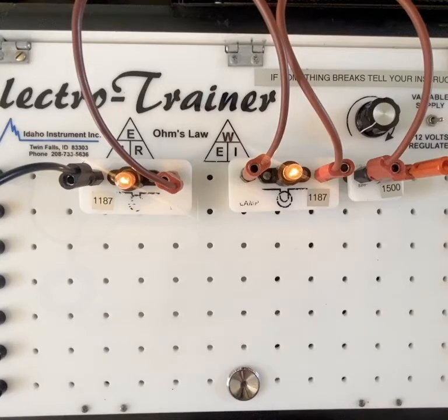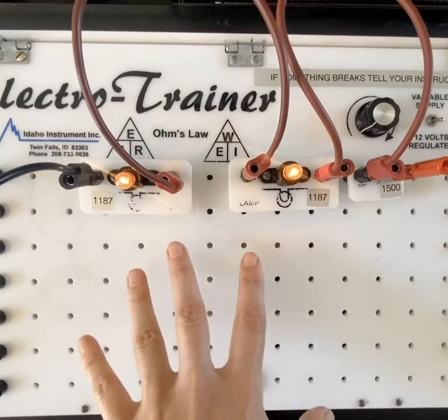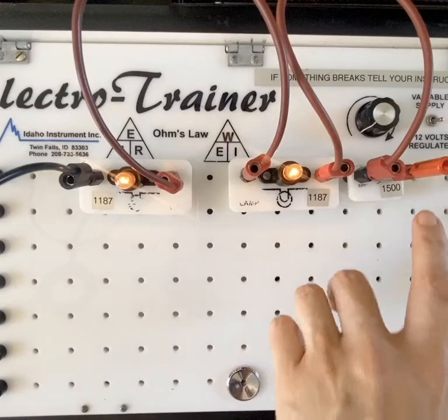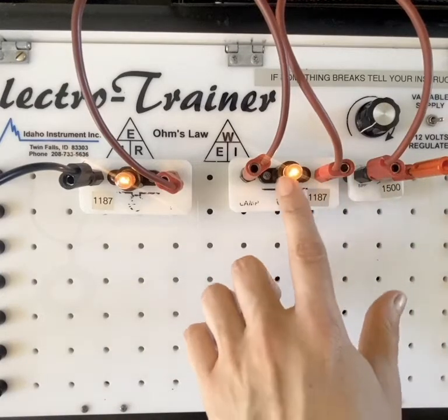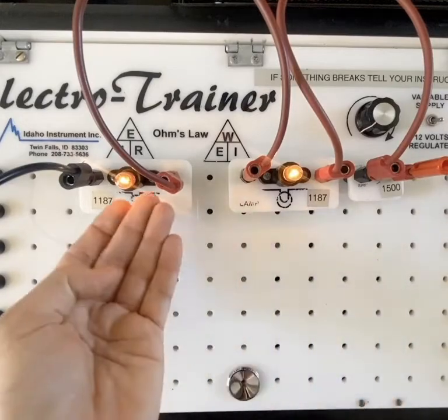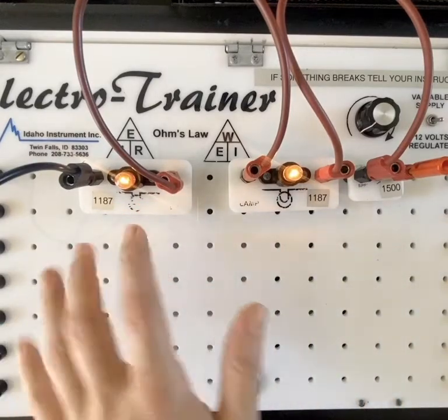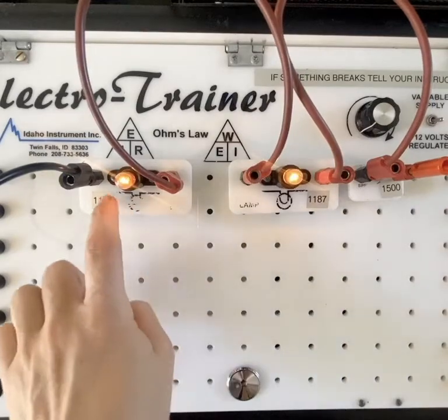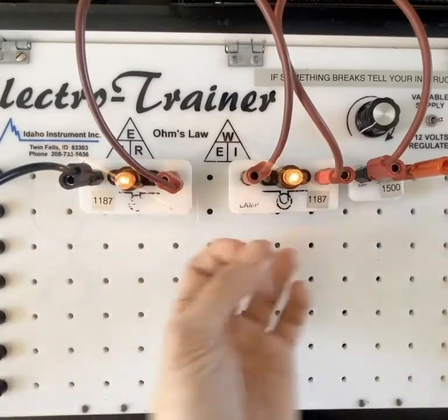One, we have less current flow, but two, and really important here, we started off with 12 volts, and first this was sort of the only child, right? It got all of the 12 volts, and now it has to split it. And we do know, because we did this up on the board, that since they're the same exact ohm value, they're going to use up the same amount of voltage.